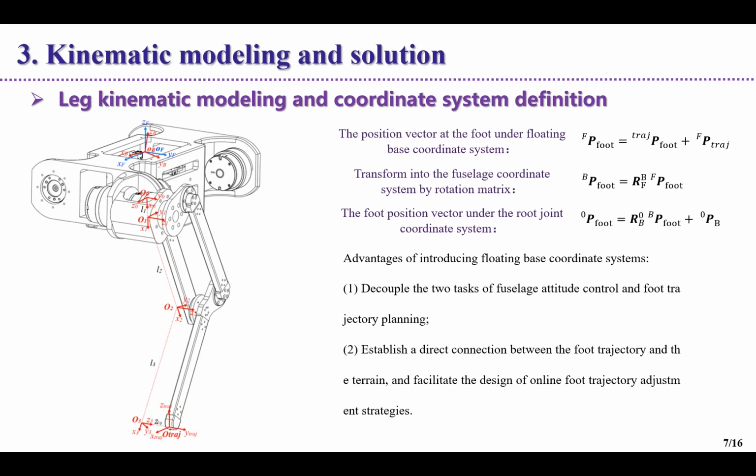In addition, the floating base coordinate system is introduced in this research to make the foot trajectory planning independent of the body posture. As shown by the blue arrow, the origin of the floating base coordinate system coincides with the body centroid.